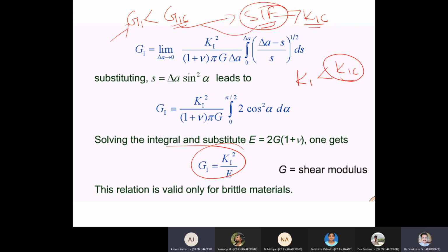But from a practical point of view, the stress intensity approach is very important. From a practical, experimental point of view in fracture mechanics, K is good. Using the same K methodology, you can use it in J also. The same procedure you can use in J also. But J is an energy-based approach.